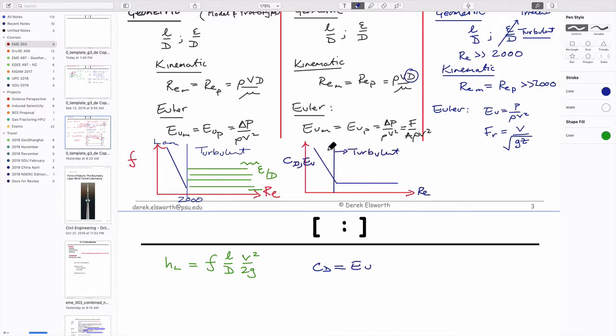And to the other side, it's laminar. And so you see a striking similarity in these figures. This is the drag which is on the exterior of a body, a water tank or something, or the nose of a plane. And it changes in characteristics from laminar behavior, where it's dominated by viscous forces, to turbulent behavior, where it's dominated by the mixing of the fluid. But it looks identical to the behavior for the internal drag.